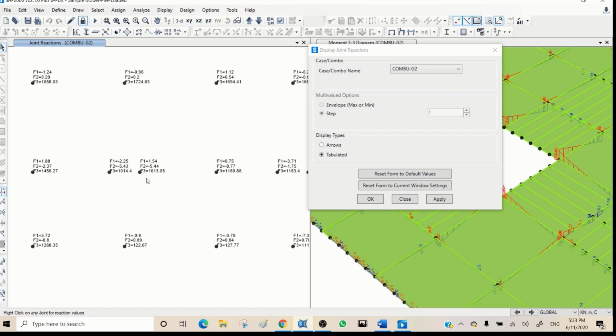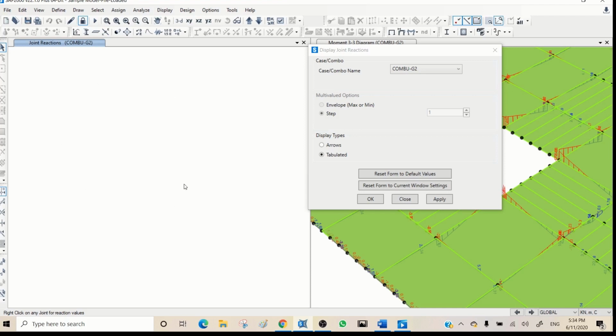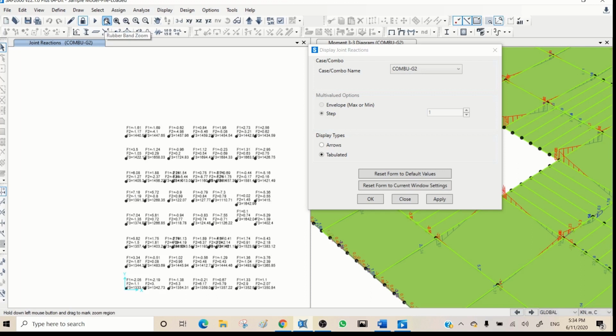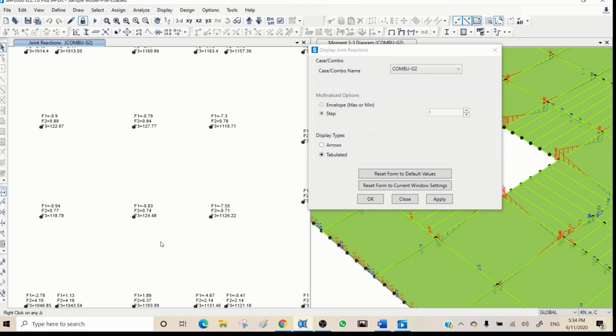That's why this column with 2 piles is settling less, because it's strong, and we don't need it actually, because the other piles are taking the same load, so they are settling more, but this is not. And if I come here and zoom for the area that I had lift, you can see the numbers are pretty small, so 122 kilonewton.